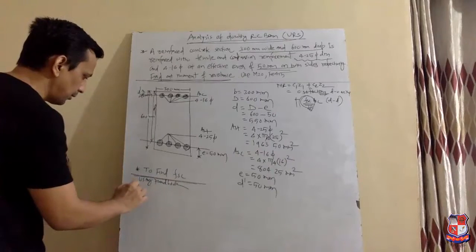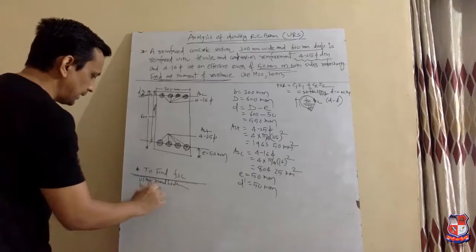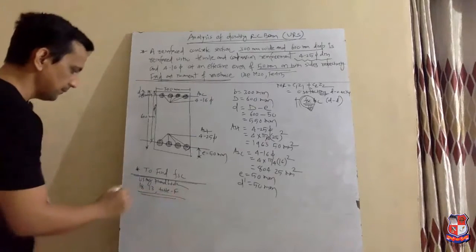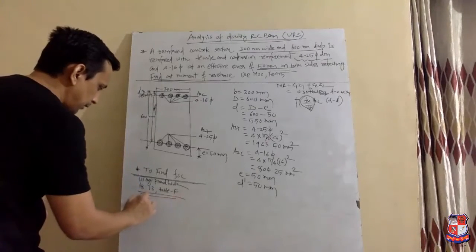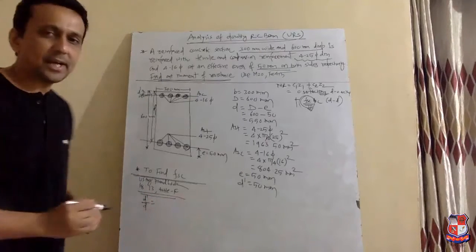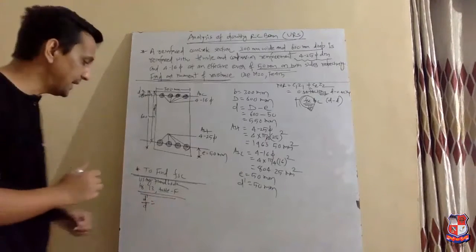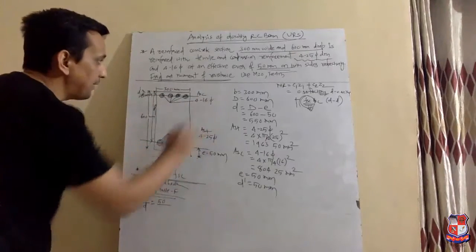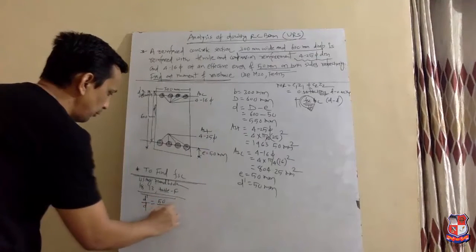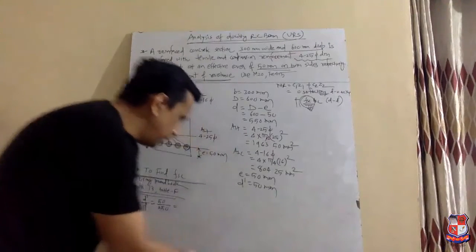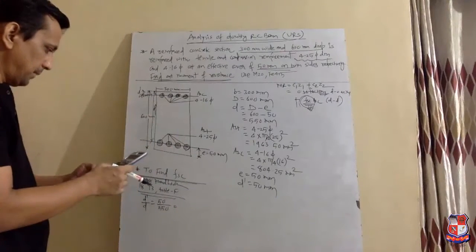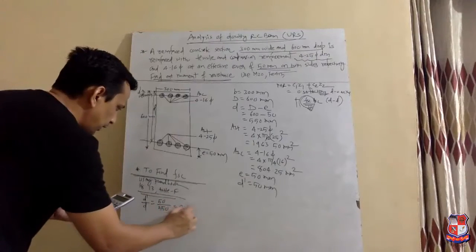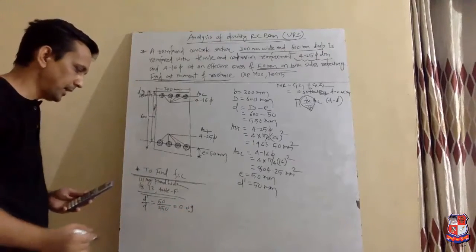In the handbook, page number 30, table F is given. For that, first of all, we need to find the ratio of d' by d. d' is given as 50 and the effective depth is 550. When we do 50 upon 550, we get 0.09, right?